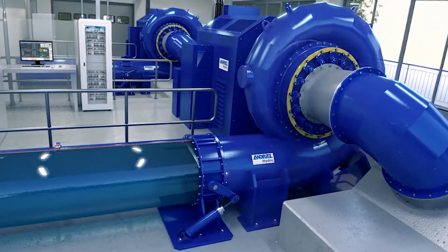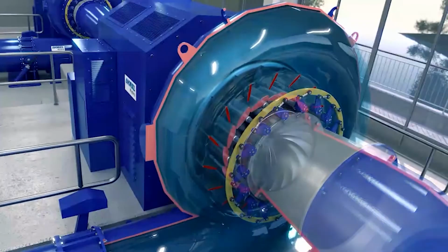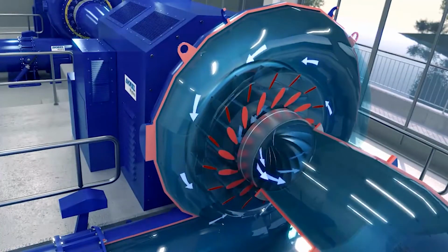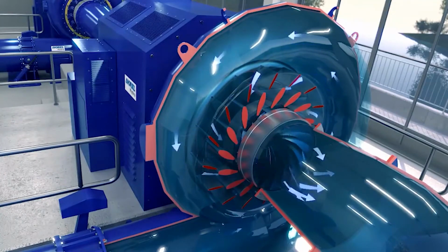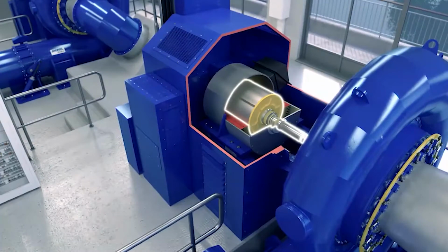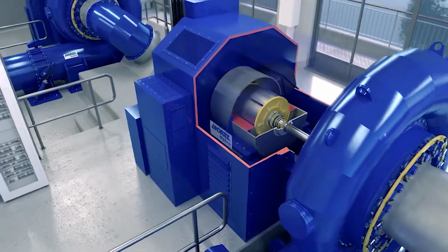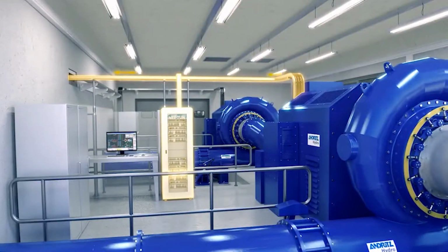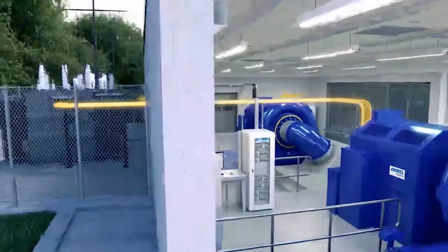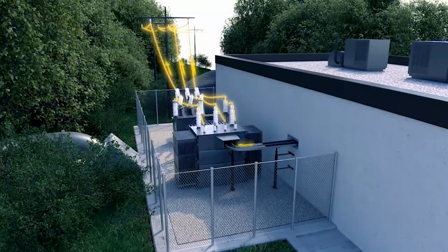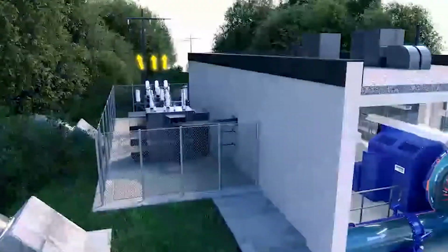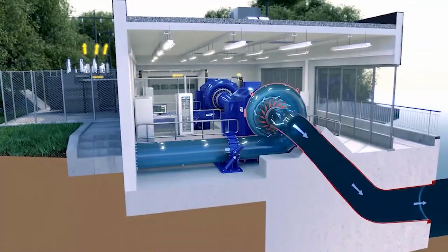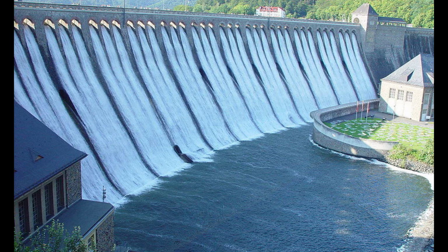A hydroelectric plant contains water turbines based on the capacity of the plant. It serves the purpose of prime mover, which converts kinetic energy of fast flowing water into mechanical energy, which is further utilized to drive the alternators generating electric energy. Energy produced is stepped up and removed from harmonics, then transformed and passed to the transmission lines. After useful work is done by water, it is discharged to the tail race and back to the river.